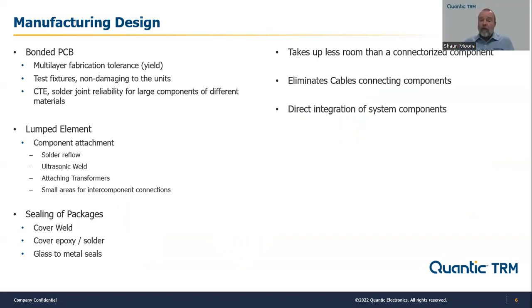There we have some downfalls in that if we're looking at a coupled line structure inside that multi-layer PCB, those coupled line structures are fully embedded in the PCB, and there's no way to go in there and adjust for any manufacturing variability. Therefore, we end up with some yield problems with those sorts of designs. We do not get 100% yield because of manufacturing variances across panels as they're being manufactured.